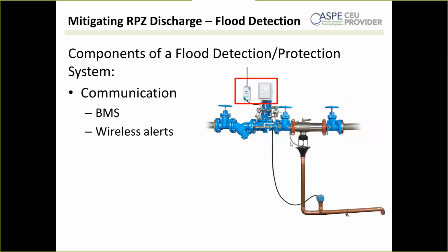So, either you're going to get a failed backflow test because there's going to be some stuff on the backflow preventer no one knows about and isn't manufacturer approved, or worst case scenario, something goes wrong. These are safety devices, right? They're in there because they're protecting our water safety. So typically your inspectors take messing with them very seriously.